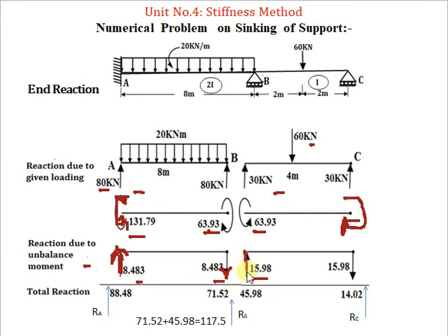Now first you have to locate that force below the maximum moment. Now there is a question of the arrow, whether the arrow should be up or down. So that arrow should be up. Why up? We need a clockwise moment at the far end. So to get the clockwise moment, this should be up, so it will rotate and it will give me clockwise moment. Now at the far end you have to take the same magnitude force 15.98 and show it opposite to the first. Now first is up, so the far end force you have to show down and its magnitude is 15.98.